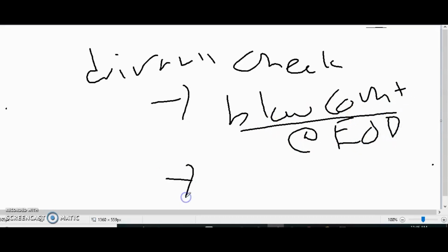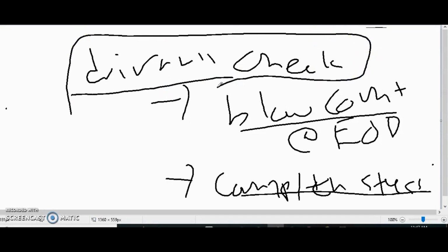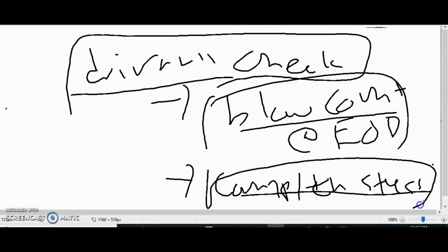And also, another important thing is the compressional and tensional stress. While the pile is being driven, the compressional and tensional stress in the pile itself should not exceed the required limit at that value. So your drivability check should include those two pieces of information. Okay.